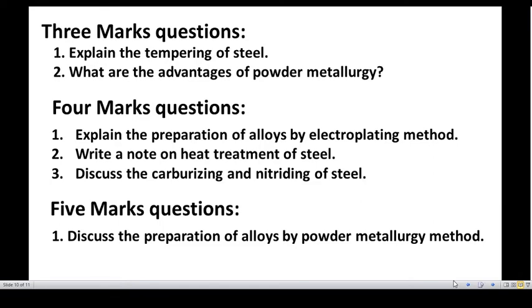So what we have to do? We have to heat the steel below a certain temperature within the range of 100 to 680 and hold the component at this temperature for a soaking period of 1 to 2 hours and subsequently cool back to room temperature. Okay, so this is the tempering. The tempering temperature is decided based on the type of steel.